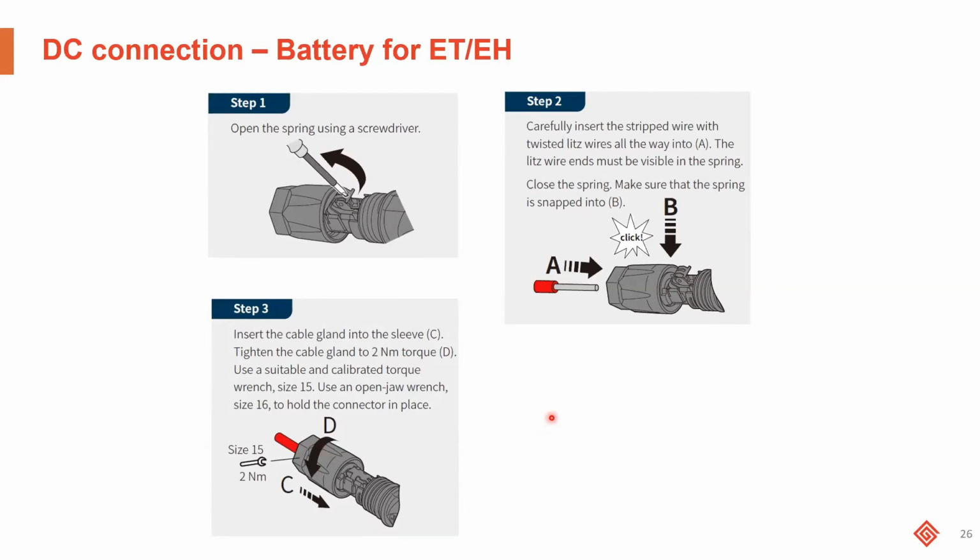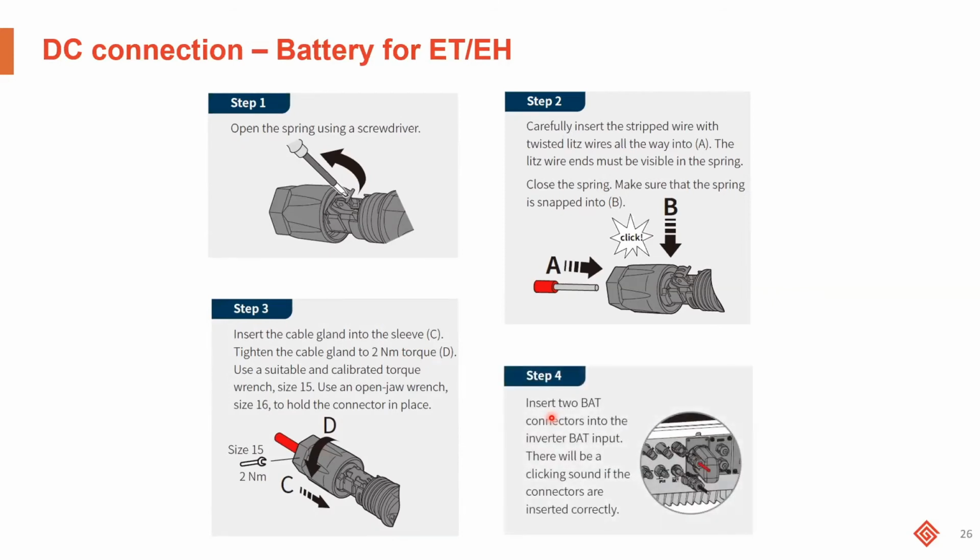One of the good things about the Sunclix connectors is that every time you push down this clamp, it actually meets that IEC standard that I was talking about with regards to crimping pins on DC cables. One of the advantages is that this pin can be pushed down up to 9 times, so you have 9 chances. After the 9th time, you will have to cut the cable, restrip it, and then use a new Sunclix connector to connect the cable.